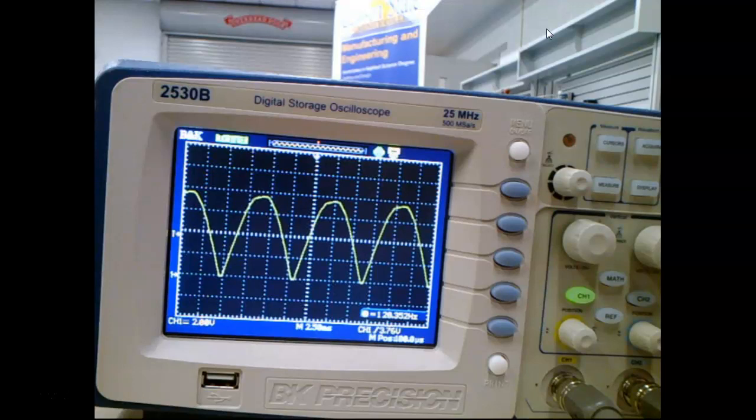So what happens is we get twice the voltage for the same input, right? You understand that? Plus now on a full wave, one of my diodes is only on at a time. So that means I could use 1 amp diodes to run a 2 amp load, right? You understand why? Because when one diode is on, the other one is off. The biggest disadvantage to this is we're having to use a center tap transformer. A center tap transformer costs a lot more than an untapped transformer, and of course we're using more diodes. So this would be more expensive, but we get more out of it, right?